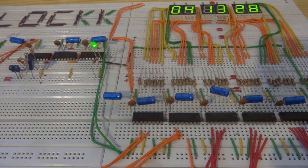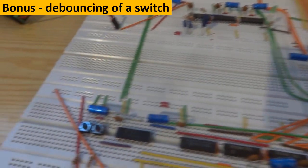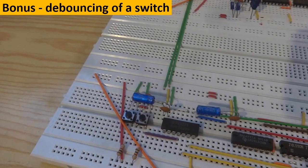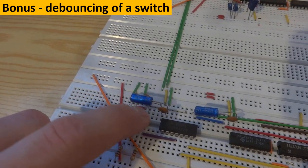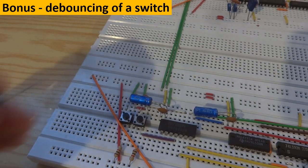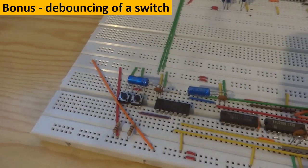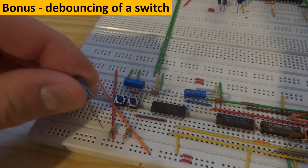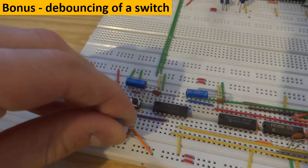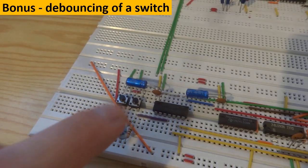Okay, so I mentioned that we have sometimes problems with multiple changes of state when pressing the switch due to the bouncing of a switch. I'll use here a capacitor connected to pull-down resistor in parallel.